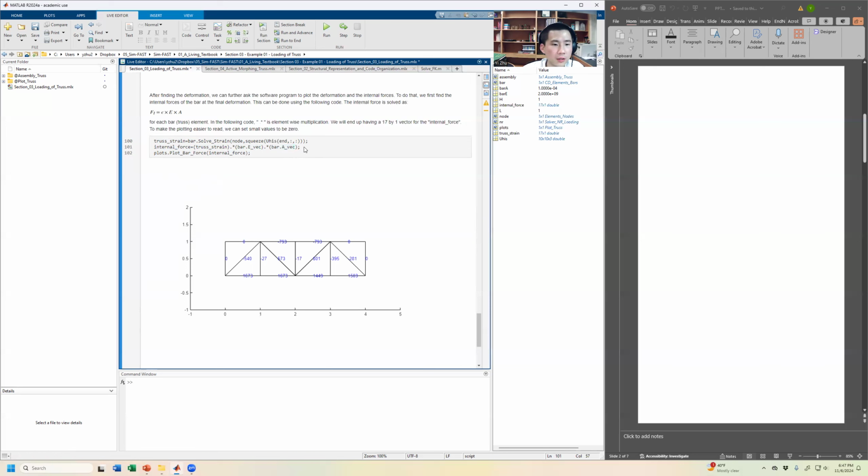So we're assuming that even under some of the larger deformation, we neglect the shrinking or expanding of the cross-section. If the deformation is small, that's usually a good enough assumption to make.